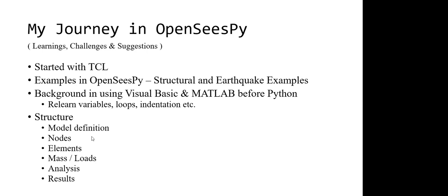So you start with model definition: defining the nodes, then followed by defining the elements. You have to go in this sequence, and then define the mass and the loads, followed by the analysis, and then results and post-processing. Basically, this is the structure of programming in OpenSees.